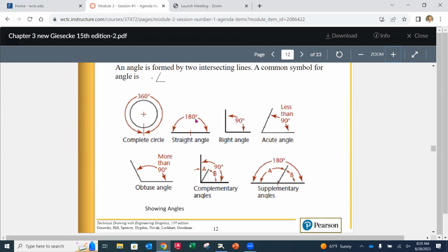So if you drew it to a specific angle and you dimension it, it's going to show that dimension to be accurate to whatever you drew it to. Sometimes we go through and we add dimensions and think, wait a second, that's not what I drew it to. Well, it is. It's going to reflect exactly how that model was drawn. Any dimension, not just angles, any dimension. You'll notice here that the dimension for an angle has two curved lines and then arrowheads. Those arrowheads are going to identify where it starts and where it stops and what the angle in between is going to be.